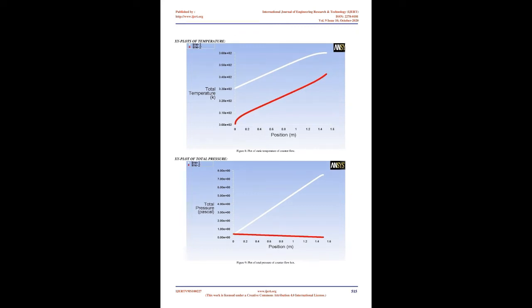4.1.2. Extrude. By selecting the first sketch in the XY plane, extrude it up to a length of 1250 mm, named as outer pipe. Again select another sketch, extrude it up to 1400 mm and name it inner pipe, and change its operation from add material to add frozen in the Z direction. By extruding the whole body and changing the operation from add material to add frozen, we have 4 different parts and 4 bodies.